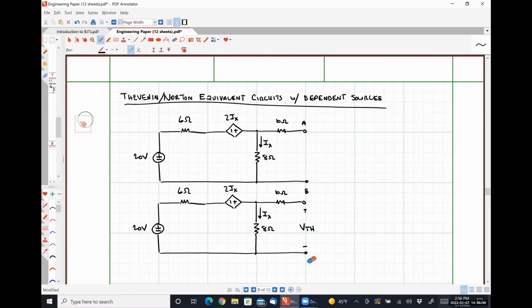So there's actually two practical voltage sources, both of which contain the 6-ohm resistor. I don't have any problems whatsoever with us doing KVL and Ohm's law to get Ix. That seems very reasonable. My question is, once we know Ix, how can we use that piece of information to determine VThevenin?